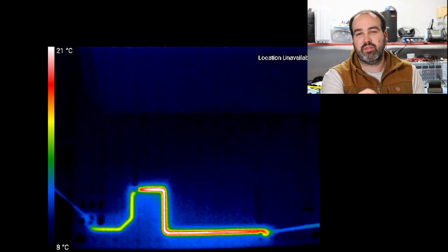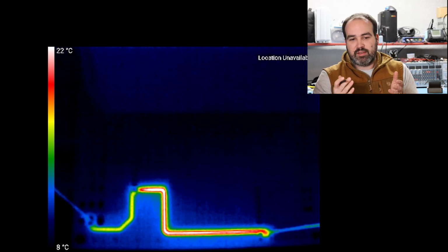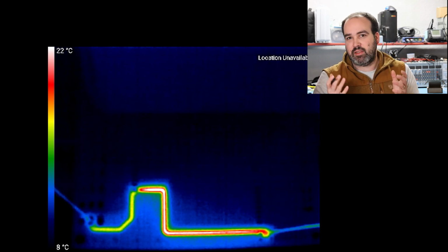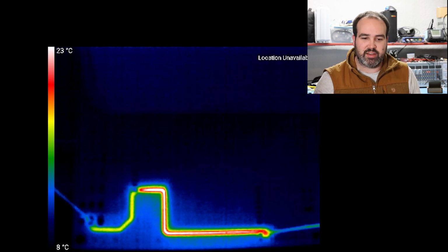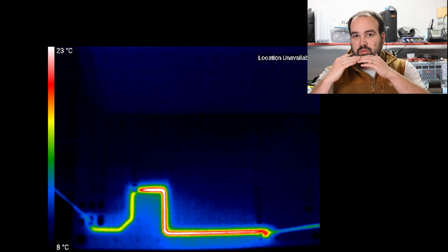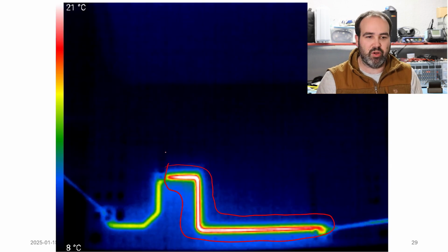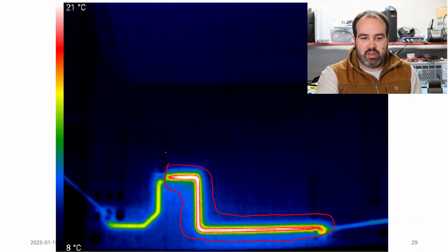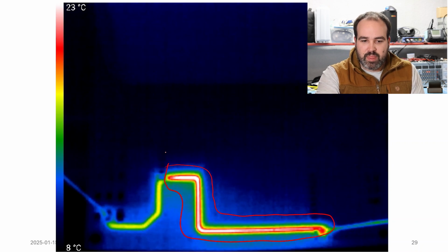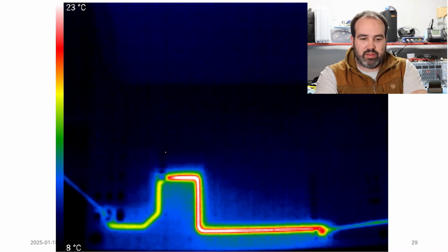It's starting to heat up, and I only leave it on for a few seconds here, but it'll start to get quite hot. Obviously, as you heat up, this is an issue because the PCB is only rated for such a high temperature, so the trace will damage the board. It can start to delaminate, and eventually would burn up if it got hot enough. So that's kind of why we also might need to adjust our widths.